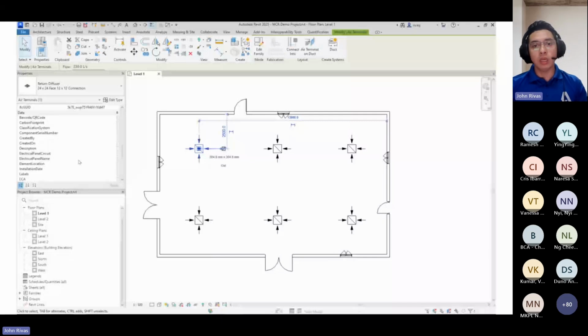So with this option, with just one click, or you can use the Dynamo player to play the script for you, it will automatically read the Excel information and then from there, bring it into your Revit projects. So currently, right now, in terms of parameter population, there are four options that I can share with you that will help speed up the process by applying the MCR parameters.